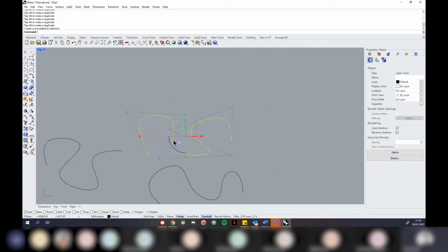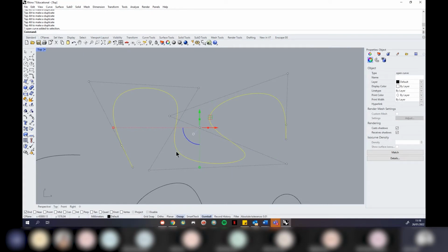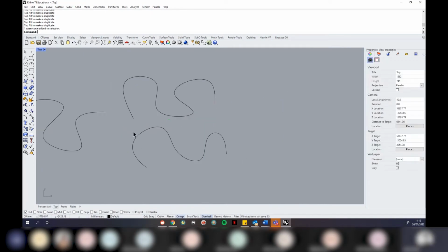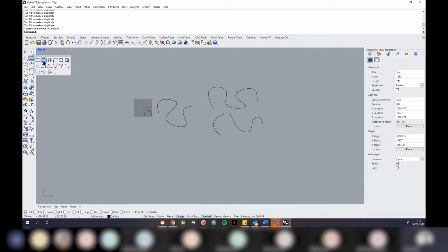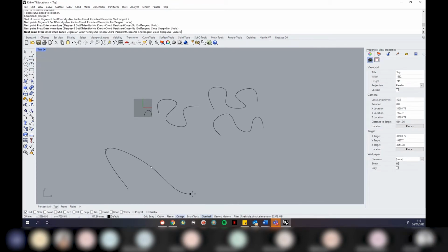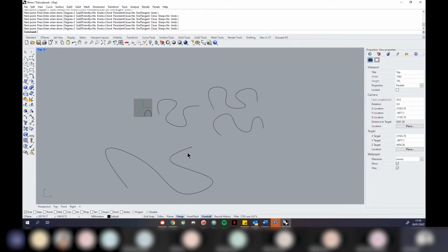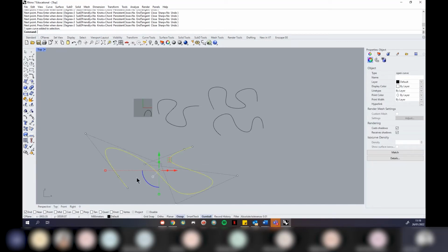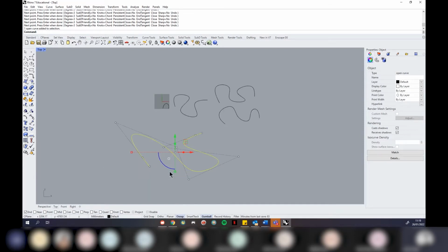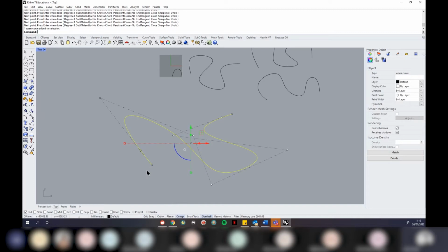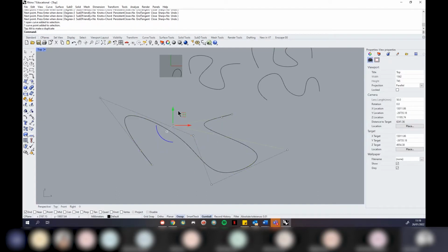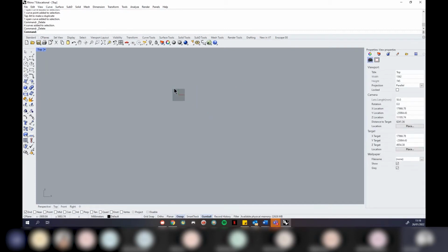If I do the same thing with this one, you'll see that, oh, hang on, this still looks exactly the same. Well, something's surely got to be wrong, right? If I go back and make my curve interpolate point again, I can see it's definitely fitting through my points, but when I select it, that's not where I left my points. Essentially, this is just the nature of how curves are defined in Rhino. So you're not going to be able to see the points on the curve, unfortunately, but you will still be able to move them around with its control points. It's a little bit frustrating, but hopefully still quite useful to understand. You're not doing anything wrong. It's just the way that curves are defined.